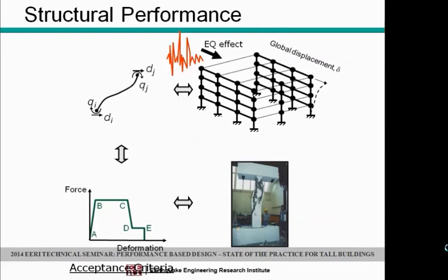The process for doing analysis has evolved a lot in the last 20 years. Nonlinear static or pushover analysis is not done very much anymore, even though most of the software that we use is capable of doing it. These days, the software we use is also capable of practically doing nonlinear response history analysis, and that's what we do usually today. And all of the tall building design is done that way.